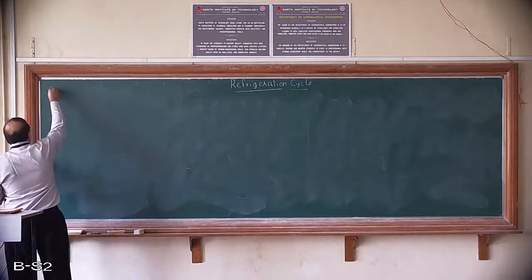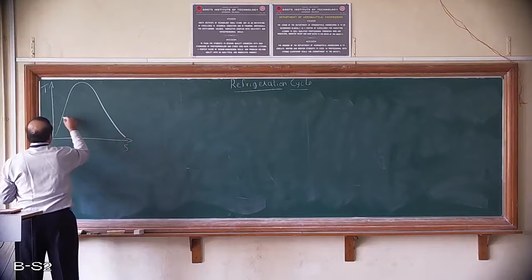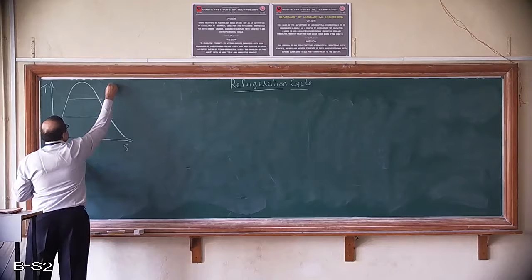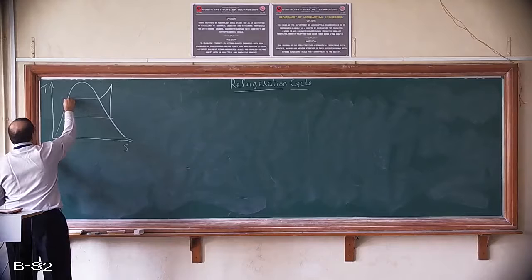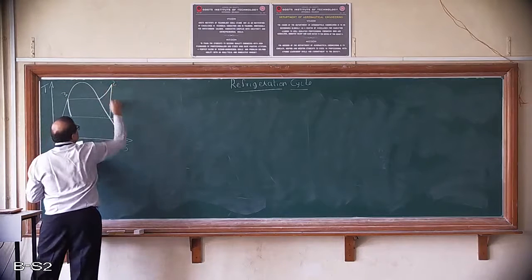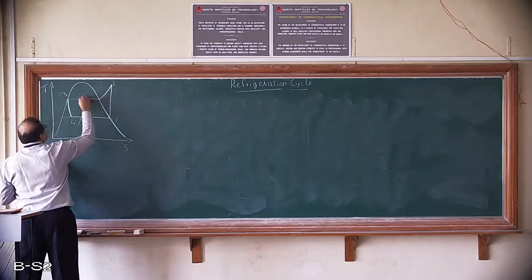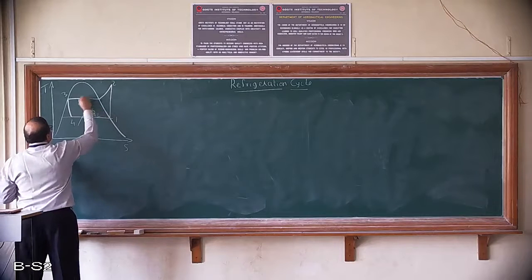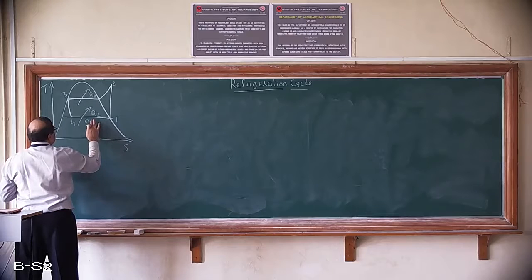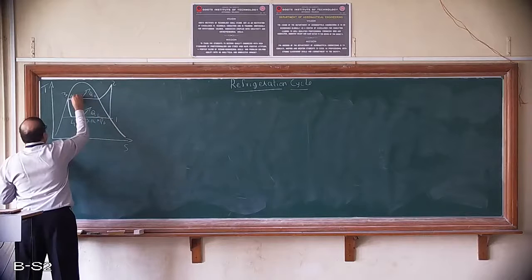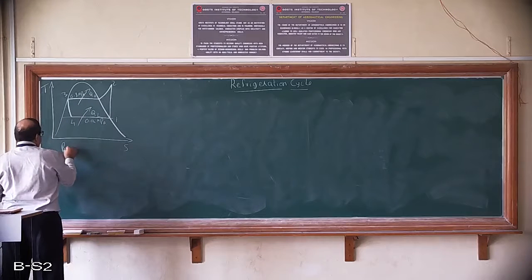First, always draw the TS diagram in this case. Always draw a TS diagram to help you understand how exactly the problem is. What is given? Refrigerant R134A.